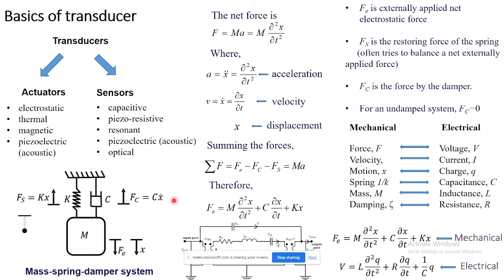When we talk about sensor characteristics, you have your static characteristics and your dynamic characteristics, right? Can you elaborate a little bit about that if you are aware of that? Yes, Dr. Aditya, thank you for asking this question. Let's say this is a simple example: we have this physical model of a transducer. If I apply a static force, let's say with the hand I pull this mass, it moves by a distance from its equilibrium position.